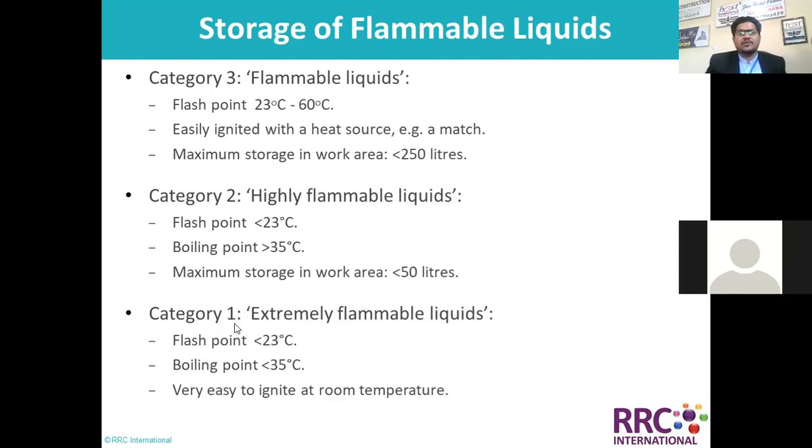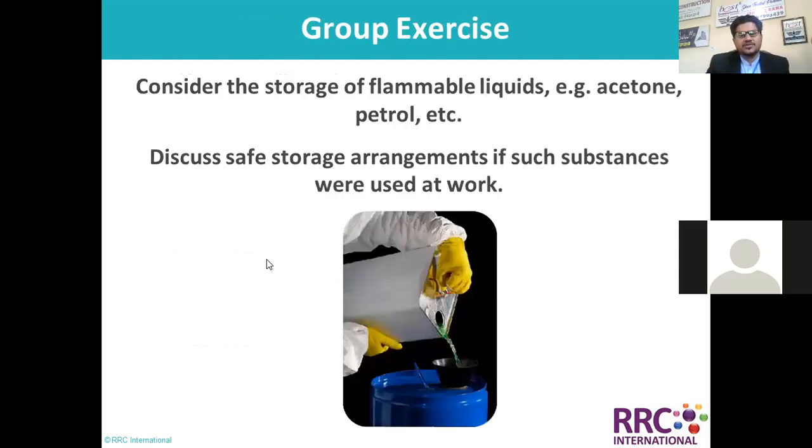In the same way, category 1, which is extremely flammable, the flash point is below 23 but the boiling point is above 35. So it is very easy to ignite, even at room temperature. So accordingly, we need to put some precautions in place here.